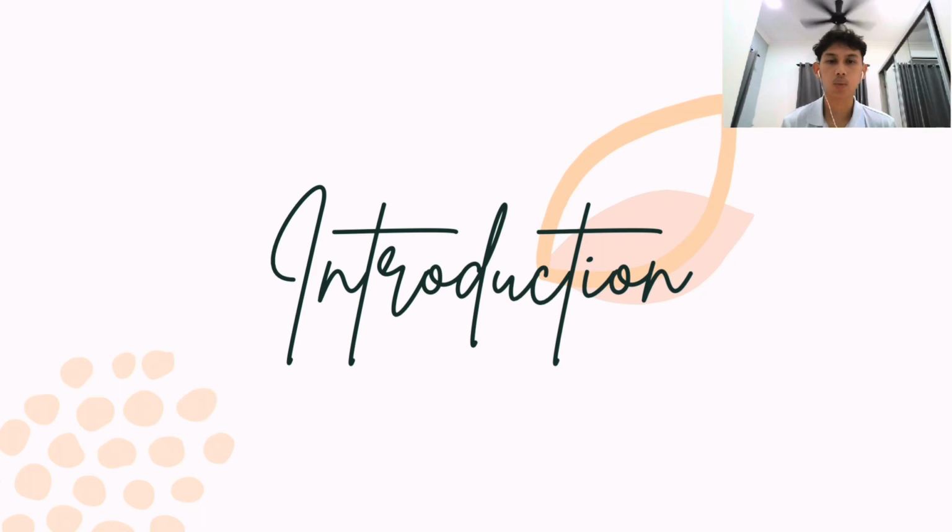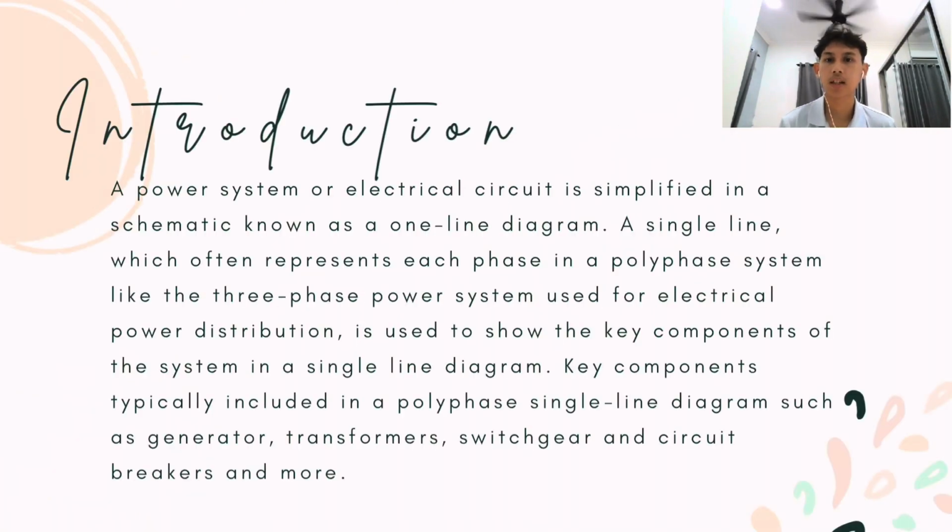So firstly, I will present on the introduction for single line diagram. Basically, a power system or electrical circuit is simplified in a schematic known as a one-line diagram. A single line diagram frequently represents each phase in a polyphase system, like the three-phase power system used for electrical power distribution. This single line diagram is used to show the key components of the system. Examples of key components used for power generation are generator, transformer, switchgear, circuit breaker, and more.